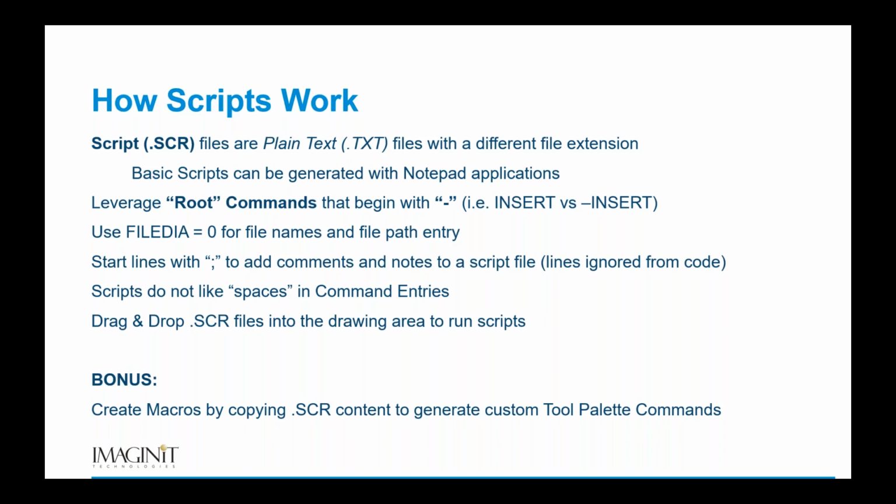If you have a semicolon, this is a question that came up earlier. Semicolons to start a line would create sort of like a note line for you. So it'll ignore that line in the code. So if you start out with a semicolon, then you can put in some notes there for what the script does or for what different columns do. And that's going to allow you to add some additional text that's not going to be read as part of the script.